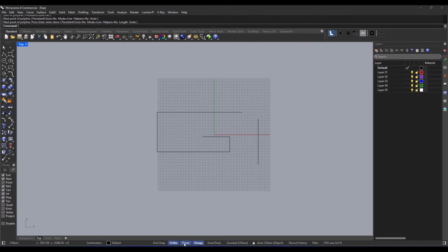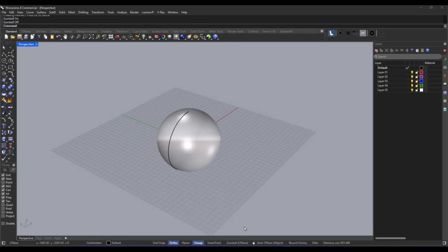All right, so here's the deal. This tool decides which plane your drawings are going to be on. Is it going to be XY, YZ, or ZX? So when you're sketching out a plan, you can totally trust that all your lines are going to be perfectly aligned on the right surface.